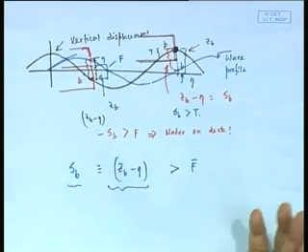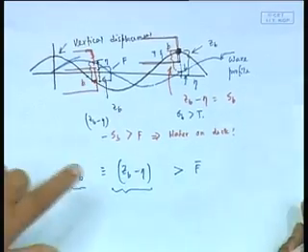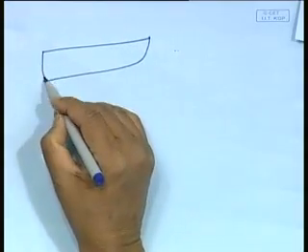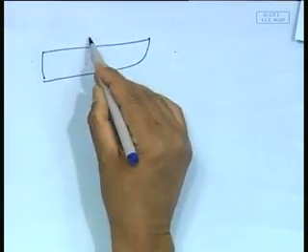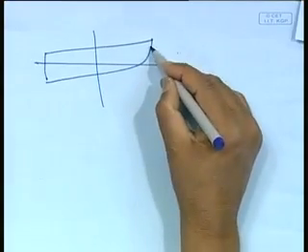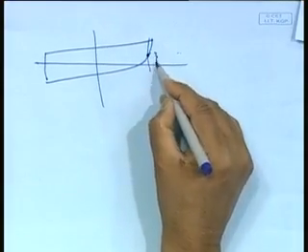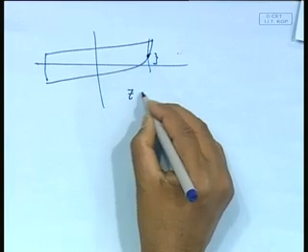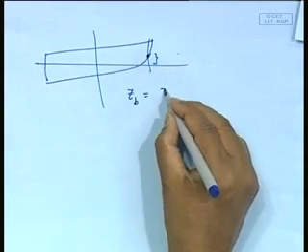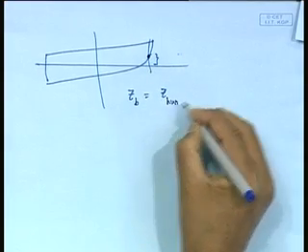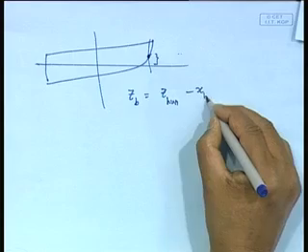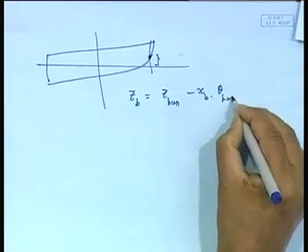Okay. That is very simple to do a spectrum, because what we have seen last time is that ZB is nothing but, once again if I were to draw a ship, with cross section etc., and if I take a point B here, remember that Z at point B is Z of the hull minus x of point B into theta of the hull, that is pitch.